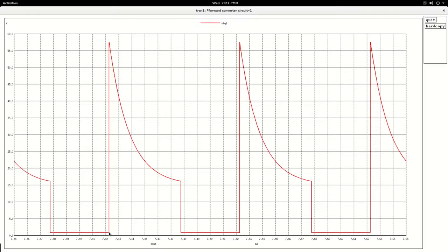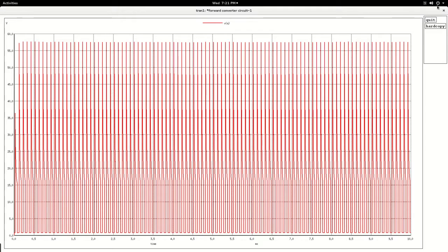This is the on time, so therefore the on state. Then the moment the BJT switches off, you see a high spike, and then the voltage decays exponentially and goes towards Vin value or VCC value. So this is typical of the lossy flux reset, and this exponential decay is the Lm by R time constant, and this is due to the decay in the magnetizing current. So this is one important waveform which I wanted to show you.